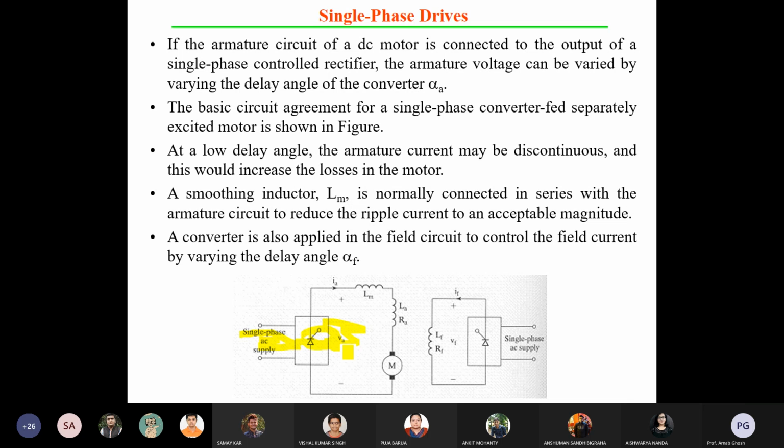Another alternative option is the IGCT. But recently you can see a lot of drives coming based on the IGBT. Maybe they reduce the voltage level on the input side, step down the voltage, and control the system. But for high power applications, that is another issue. So an IGBT set or IGCT set is what they are using right now. That's the motivation for using the SCR.